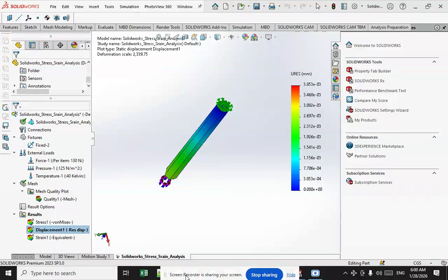For orthotropic materials such as wood, whose stiffness is symmetric with respect to each of the three orthogonal planes, nine coefficients suffice to express the stress-strain relationship. For isotropic materials, these coefficients are reduced to only two.